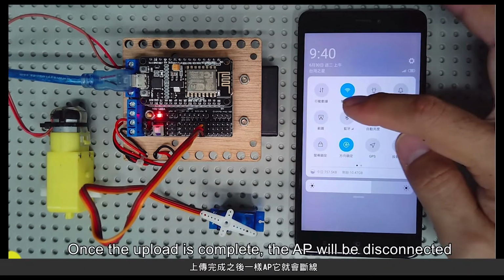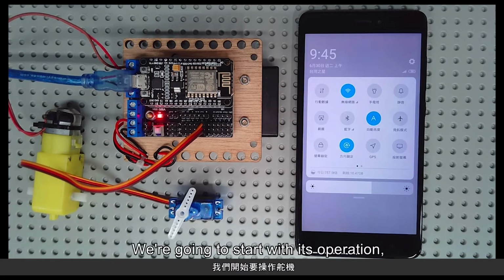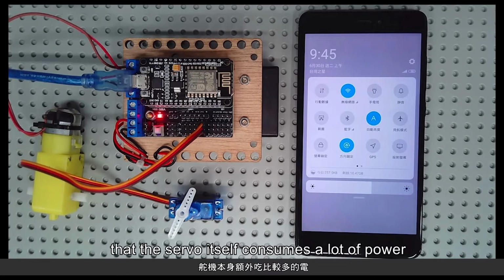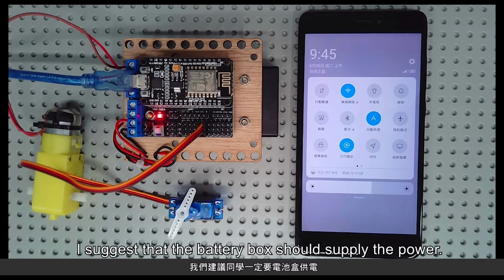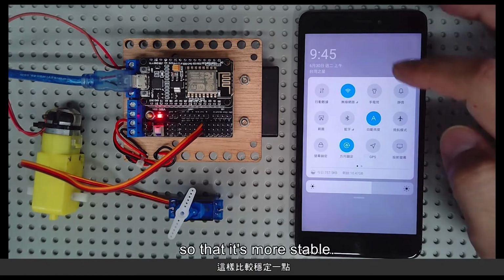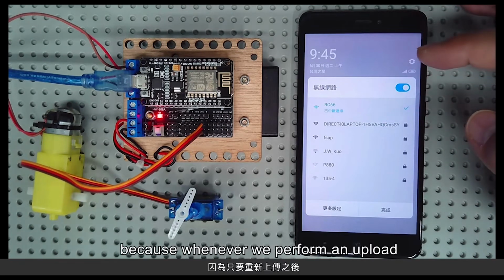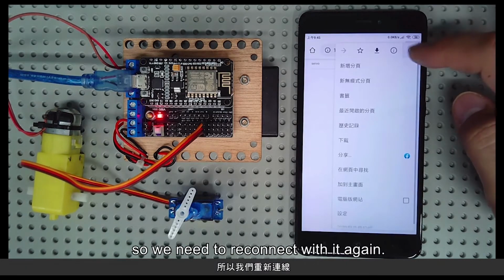Once the upload is complete, the AP will be disconnected, so we need to reconnect with it. We're going to start with its operation. Let me remind you that the servo itself consumes a lot of power, so when we're operating the servo, I suggest that the battery box should supply the power. Before plugging the USB cable to the NodeMCU, we'll use the battery box to supply the power, so that it's more stable. We'll select the AP again, because whenever we perform an upload, the AP Wi-Fi will be disconnected, so we need to reconnect with it again.